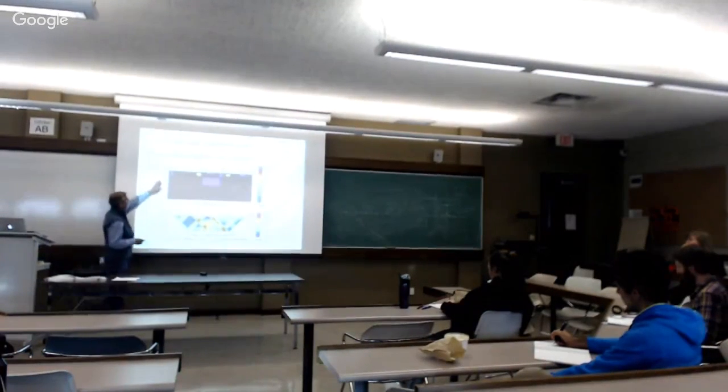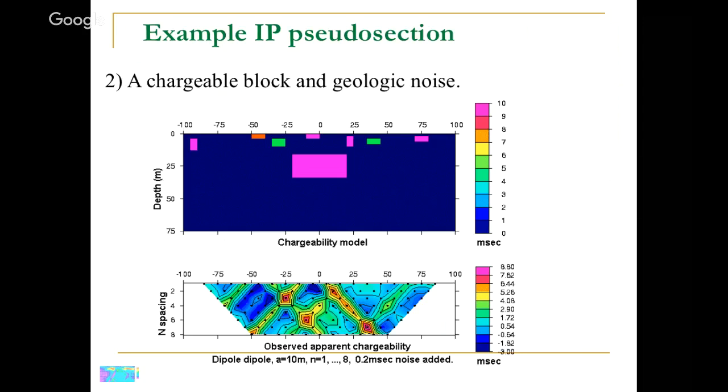Again, if we add little bits of stuff, now these things are all the same conductivity, no change in conductivity, but they are different chargeabilities. And again, clays, graphites, sulfides, those are the big ones, and perhaps from your perspective, clays are important. So if you had something that looked like that, then now your pseudosection just gets all bundled up, and you just can't see anything.